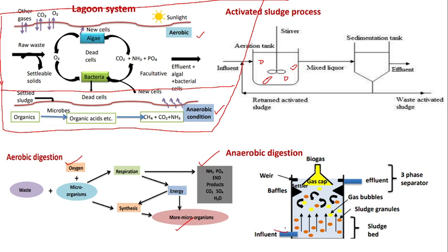So when the wastewater is coming in, it is going to form a sludge here. Sludge granules will be formed here. Extreme pressure conditions will be prevailing here since it's a very closed environment. Because of the pressure, it releases biogas, which is methane. So anaerobic decomposition of the organic matter happens here. And then the effluent water alone will be collected outside and goes to the next step. So these are the methods involved in the secondary treatment process.